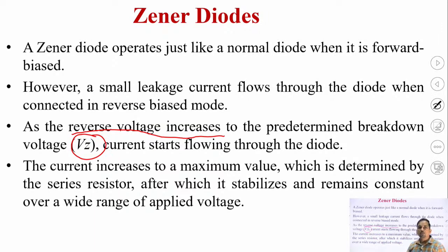it has been observed that the current starts flowing through the diode. As we further increase the voltage, the current reaches its maximum value. If we increase the voltage further in a conventional P-N junction diode, the diode generally breaks down. But in a Zener diode, if we further increase the voltage, it maintains a saturated voltage Vz.